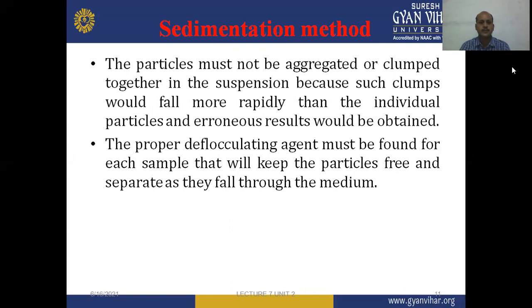We can use a proper deflocculating agent, which must be found for each sample, that will keep the particles free and separate as they fall through the medium. We can then obtain accurate results. So a proper deflocculating agent must be used in this experiment.